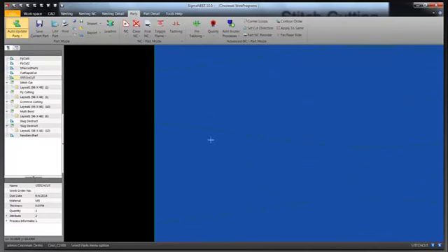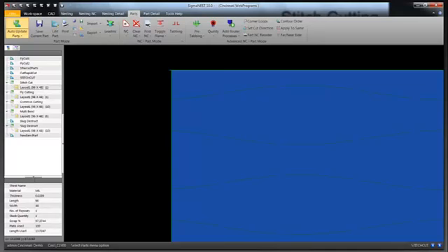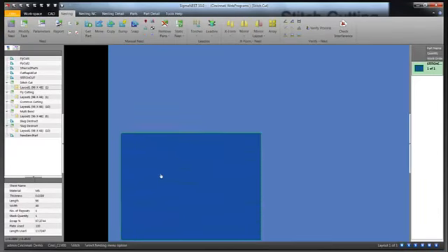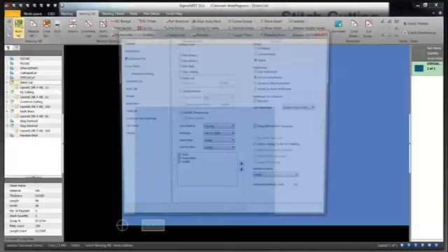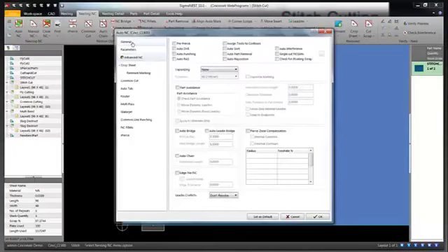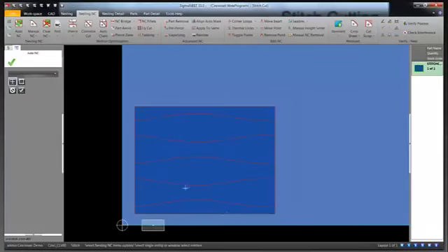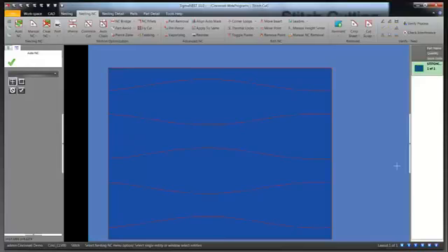So what we do, and the idea of this, is to cut these things and position these parts all back on top of each other, and it forms a square such that when we cut through the middle of one of these things, it is a form of common line cutting, but we also have a tab in there to hold the parts together. So now we can roll this entire set of parts up in one shot. Once again, thinking in terms of the next process to decrease time there. You want to go ahead and simulate that, Seth?